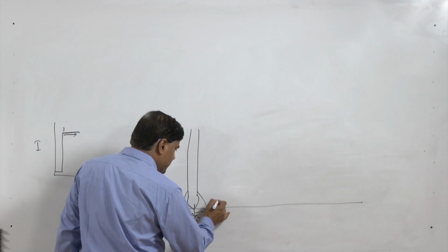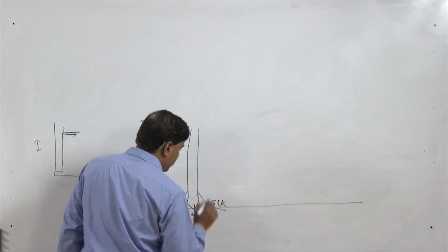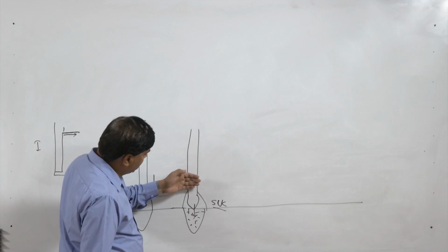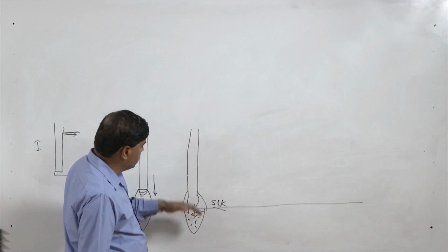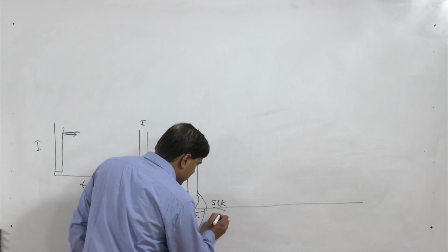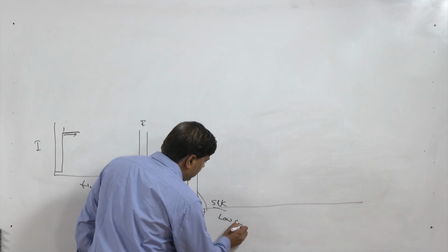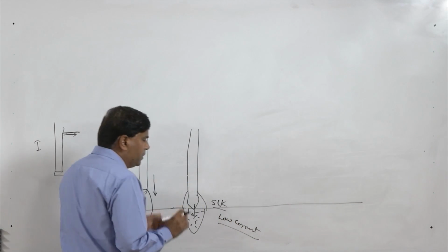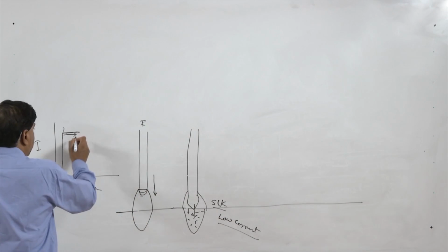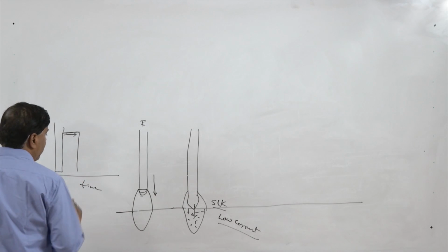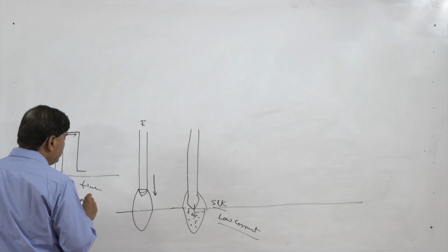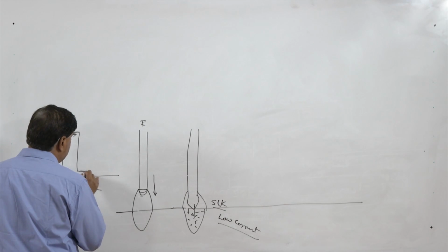In this case, short circuiting will take place. So the transfer is just by touching the pool, the circuit is completed between the electrode and the pool. So short circuiting takes place, but at this stage very low current is ensured. So the transfer is very smooth because current magnitude is reduced. So at this stage of short circuiting, current is lowered.